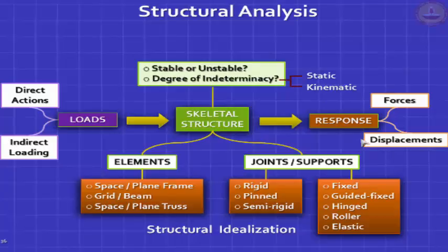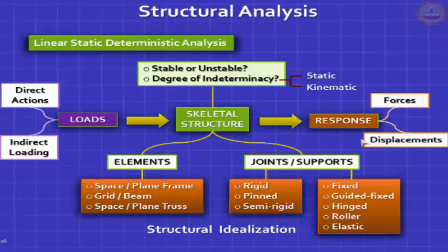We looked at static determinacy, but there's also kinematic indeterminacy, and most problems in practice, multi-story buildings for example, are both highly indeterminate statically and kinematically, and you have two approaches. One is called the force approach, where you look at static indeterminacy, also called the flexibility method, and the displacement approach or the stiffness method if you look at kinematic indeterminacy.